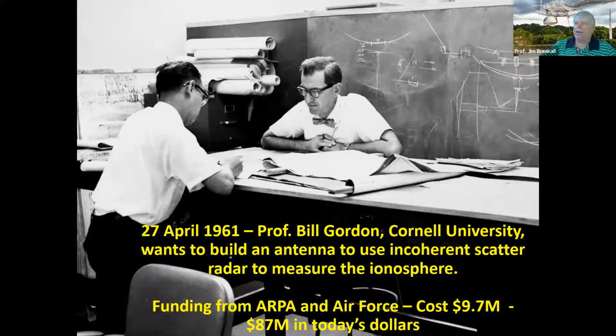And it turns out there is a limit to how far you can move the antenna, because you run out of the dish. If you keep moving to the side, eventually, because it's a truncated sphere, you're going to run out of the dish, and so the energy is going to go down as you move to the side. But Arecibo could get pretty much good performance from straight up, which is called zenith, out to plus or minus 20 degrees. So there was a 40-degree angular sector that could be covered, and then of course all the way around in azimuth.